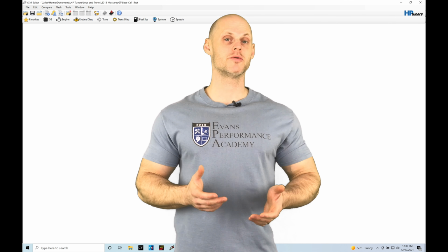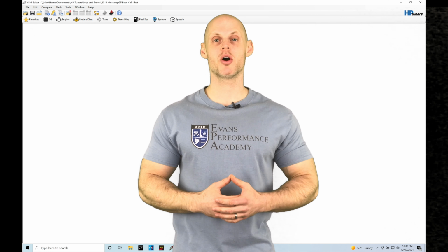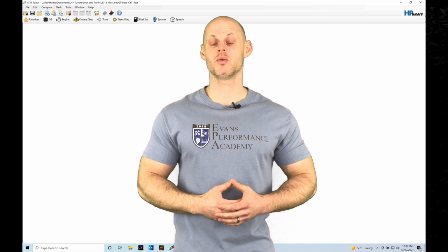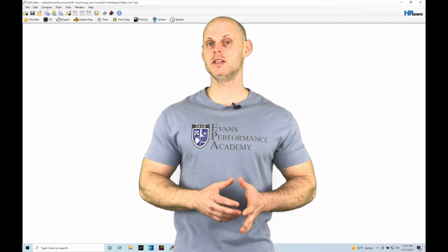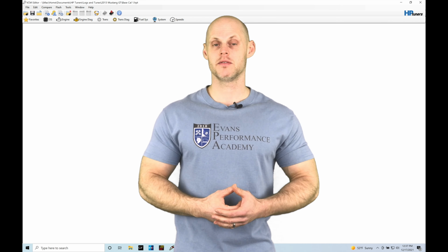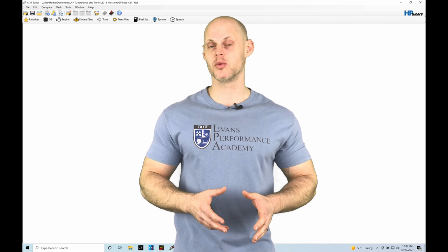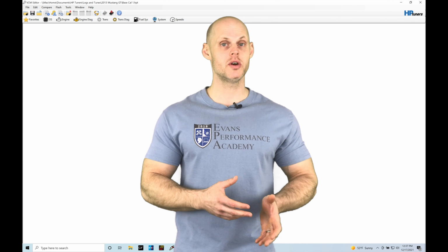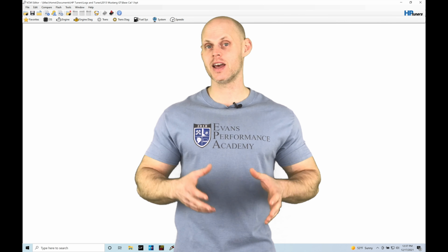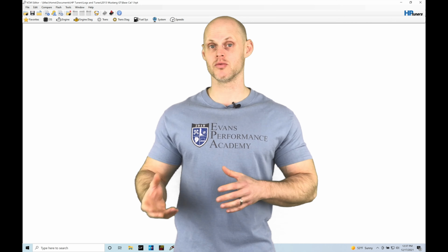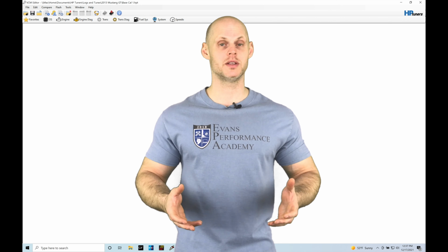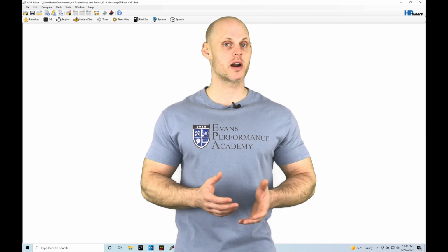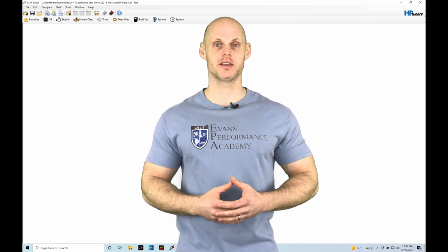Welcome to HP Tuner's Ford Gen 1 Coyote Training Part 21. In this training module, we're going to be taking a look at working with our VCT scheduling basics. The VCT scheduling is going to be how the variable cam works within the Ford Coyote engines. We're going to break down all the tables and how they fit together in order to command the cams to rotate at various different points within the engine's operation. We're going to have a lot to cover. Let's jump in so we can check this out.